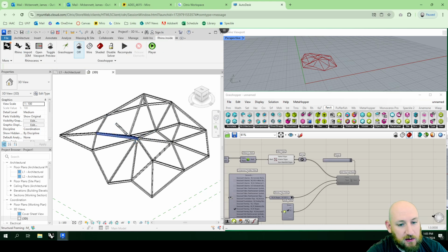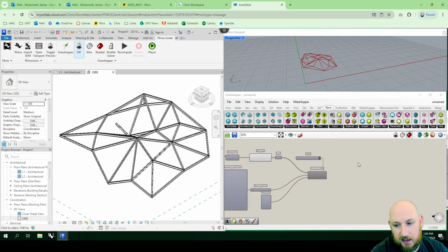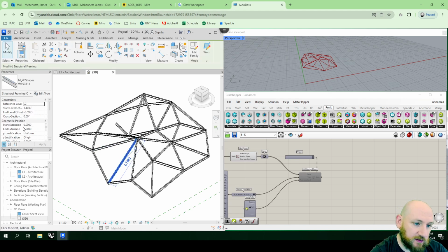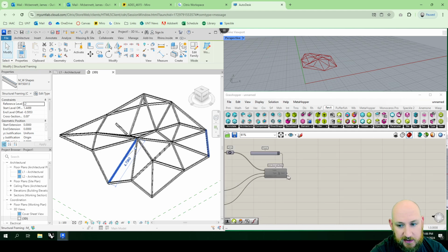Now I want to shrink all of these beams by 0.25 on both sides, which will be minus 2.5 because I'm shrinking all of them. But I don't want to do that manually. So instead, I need to do something similar to this idea of selecting them, then finding the name of the parameter you want to edit, and then editing it. That's what I'm going to do after I create these beams.